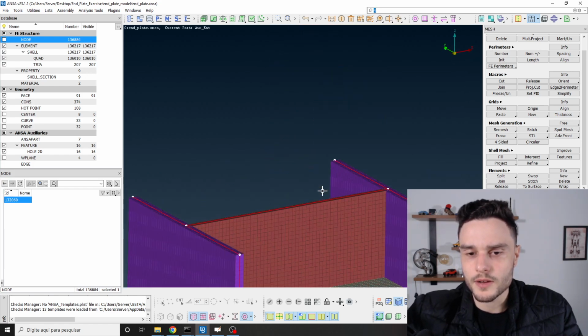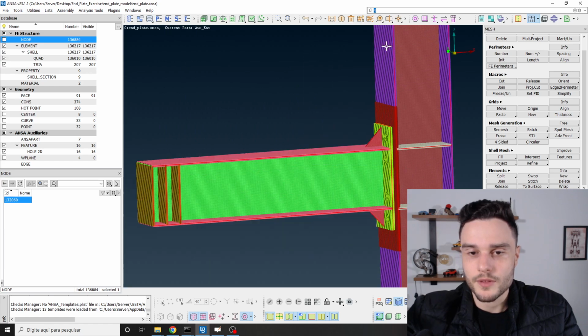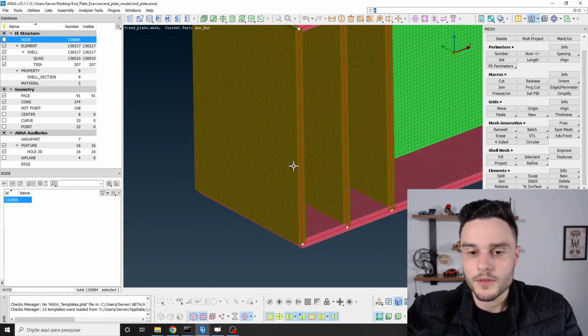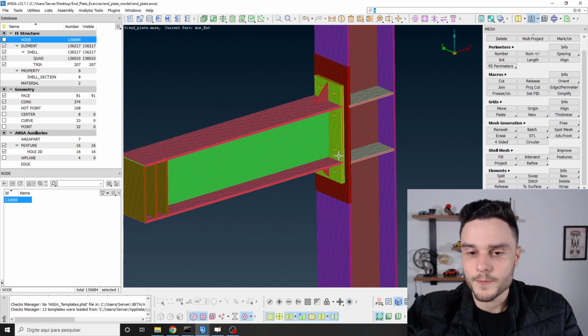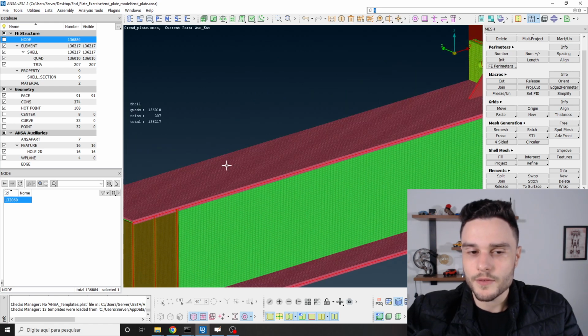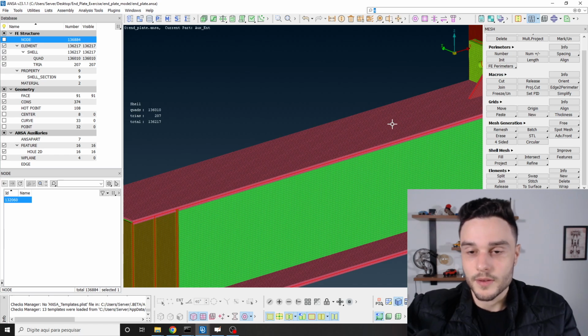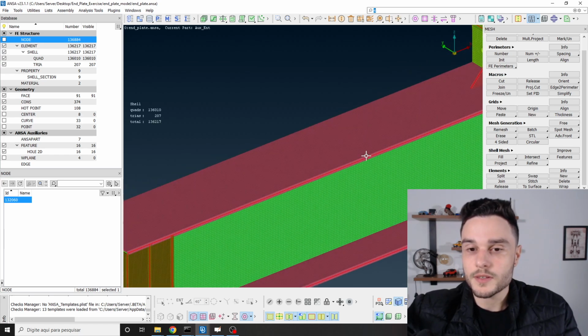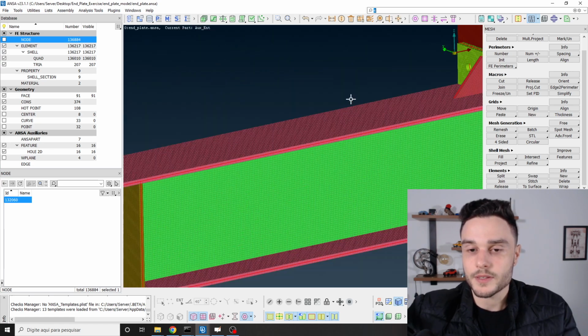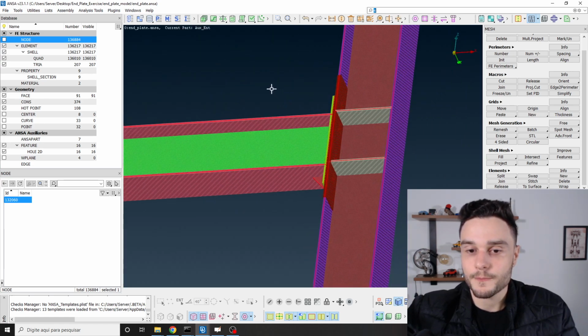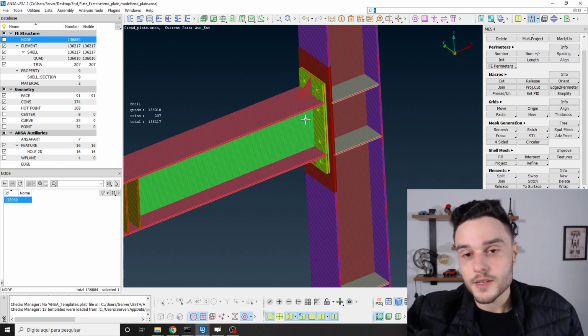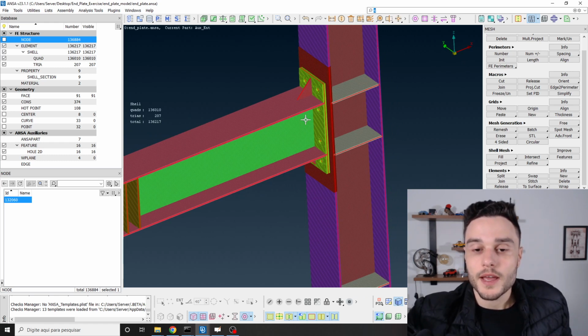Okay, so you can look around and visualize the thickness of the element. Everything looks okay. So you see that we have assigned the thickness to the face, and we created a mesh on the face, and because of that, the thickness of the shell that is defined on this face is the same as the thickness of the face. Okay. All right, so that's it that I had in this video, and see you in the next lecture.